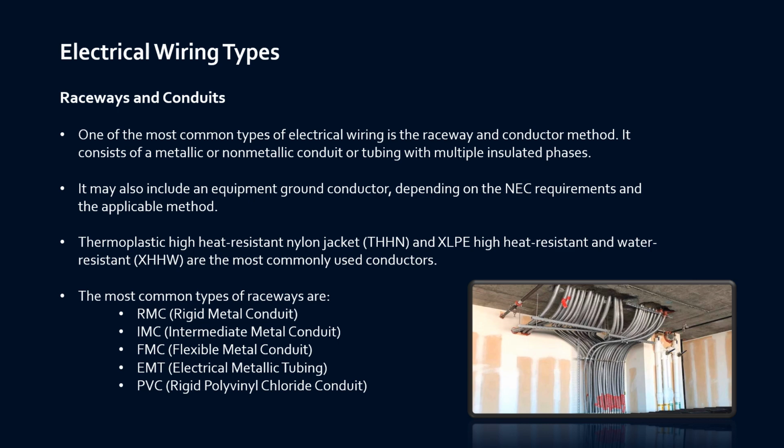Thermoplastic high heat resistant nylon jacket, or THHN, and XLP, high heat resistant and water resistant, are the most commonly used conductors. The most common raceways are your rigid metal conduits, your intermediate metal conduits, your flexible metal conduits, or electrical metal tubing, or your rigid polyvinyl chloride conduit.